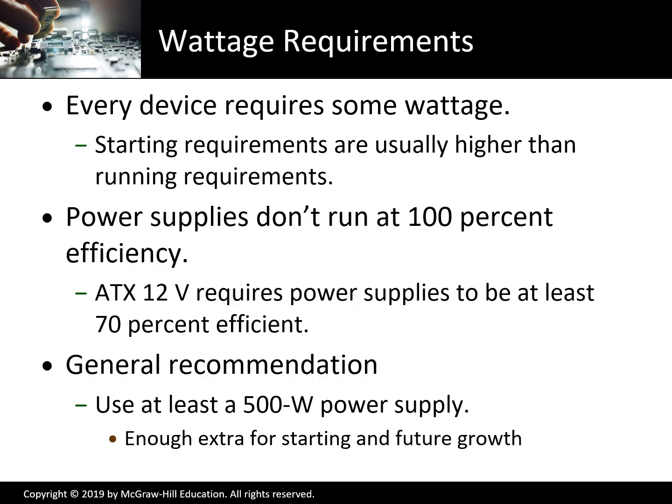Now, wattage requirements. What do you need to run a computer? Most power supplies today will run somewhere between 400 to 1,000 watts. They don't run at 100% efficiency. So if you're putting a bunch of stuff on it, a bunch of drives, etc., you probably want to go up to the higher 750, 1,000. If you're just running a basic computer, you'll probably be able to get by with 500 watts.